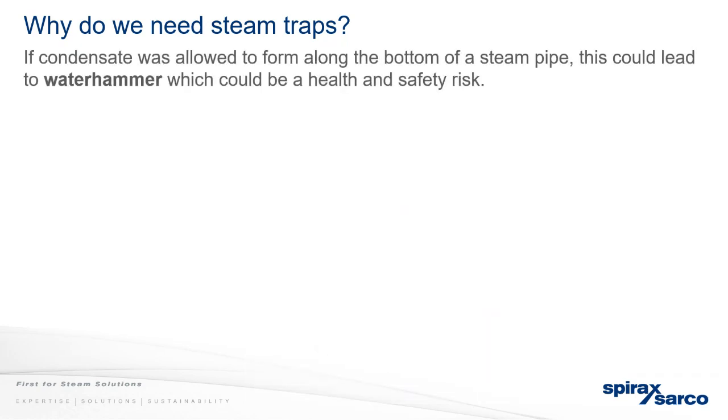Condensate is allowed to form along the bottom of the steam pipe. This could lead to water hammer, so that's why we need to get rid of it, which could cause health and safety risks. So, water hammer in a pipe, as we get to the next slide.